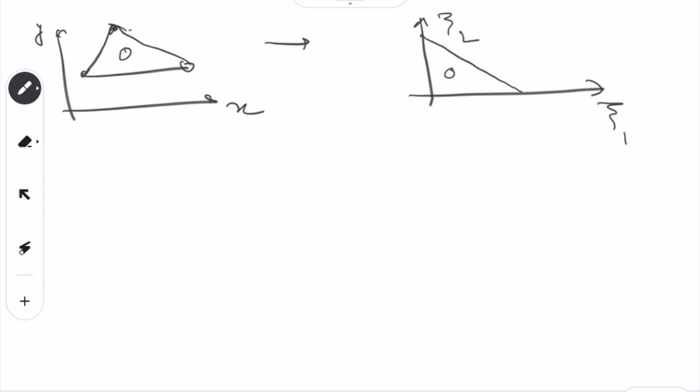So basically what we want here is how to construct a shape function for this one. We can use the triangular system, like we said, this is xi, eta, and this xi1, xi2 and xi3 system. We know that the value here will be xi3 equal to 0, and here will be xi3 equal to 1 at this point. So we can write xi3 equal to 1 minus xi1 minus xi2. So this system also we can have.